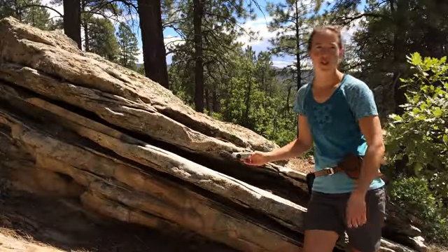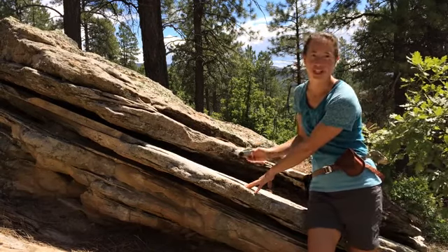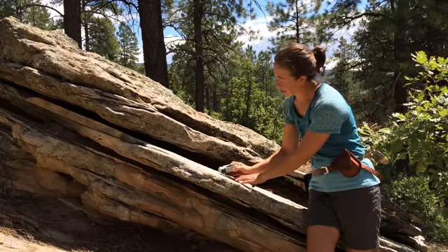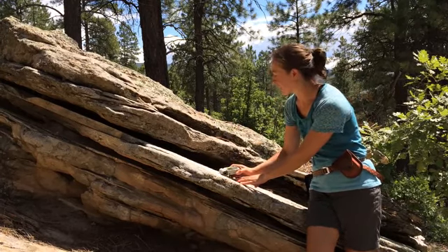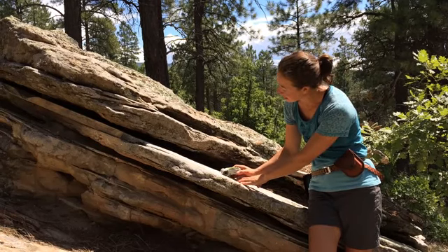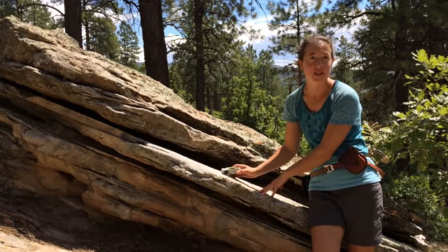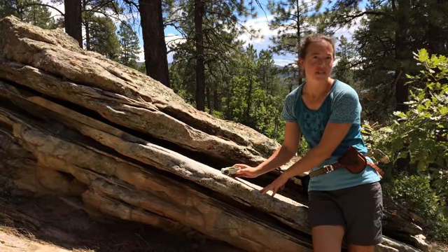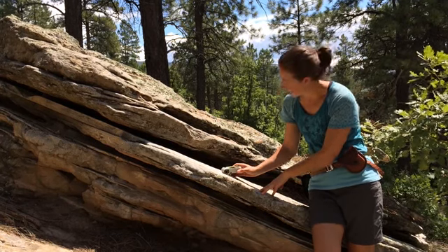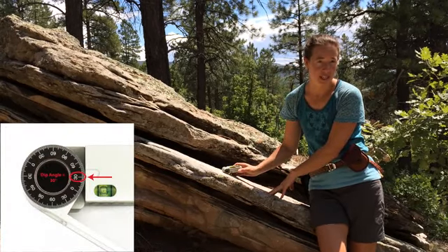I could also measure the orientation of this same plane using the alternate configuration of the lid, where I've rotated it around its minor axis. This method doesn't have any advantages over the other, except that it helps visualize the horizontal plane and dip angle even better. In this alternate lid configuration, the only thing to do differently is to read dip angle at the bottom of the dip indicator.